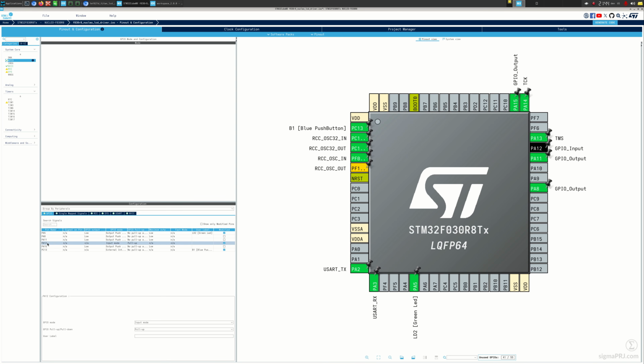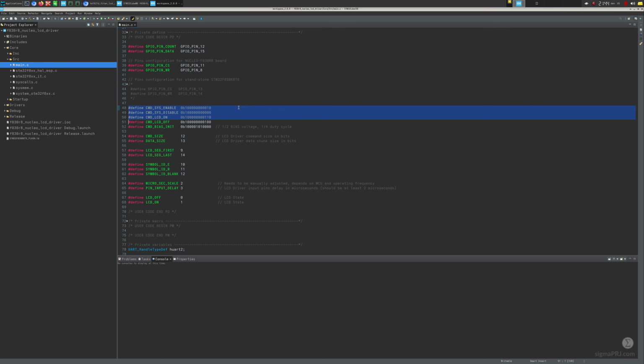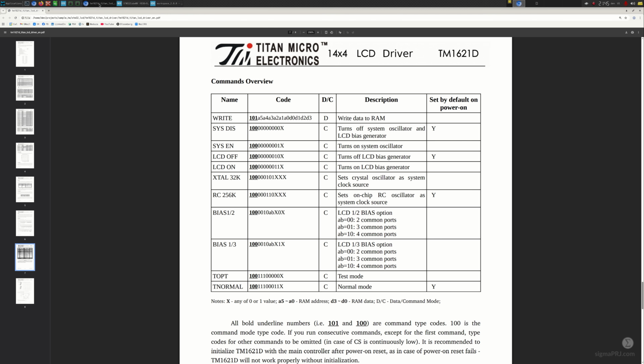This will be driven by the count button, and we have to set it up to pull-up mode. 3 output pins also have been defined. This will be used to control the LCD driver. Timer 6 also needs to be enabled as well, on a later stage, once we use the second application sample with a ticking counter. And here we have the LCD driver's commands themselves. This is configured based on datasheet specifications, which we have reviewed previously.